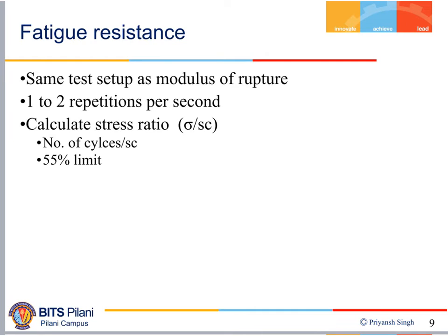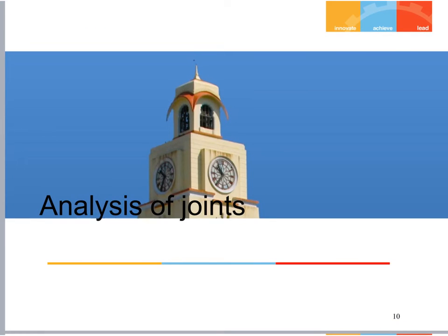These are the important properties or parameters corresponding to cement concrete which will be required in your rigid pavement design. Now, when you lay your concrete in the field, there will be a normal temperature of concrete, let's suppose 25 degrees Celsius. But after this laying work, during the day, the temperature may go up, or during the night, the temperature may go down.